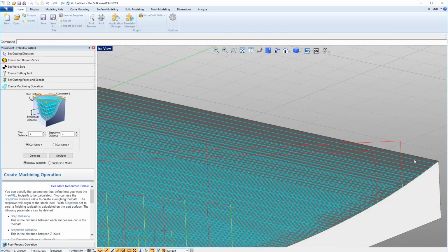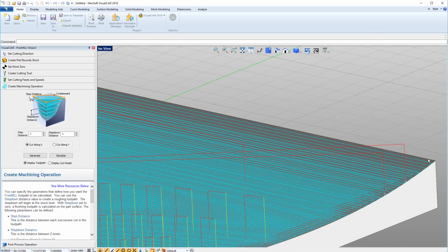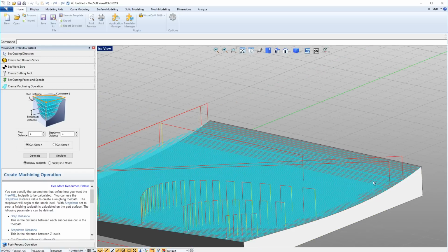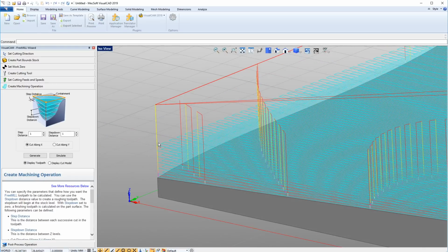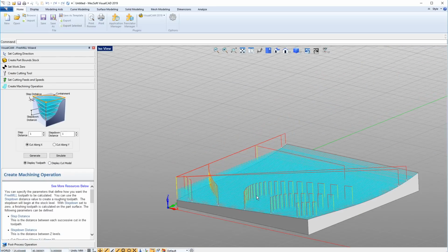So look up here, we can see my depth of cut is like 1 millimeter. So for that first bit up there, the whole depth of cut is right on the surface. So you can see those lines. That's the tip of the tool. It's following those lines on the surface. And then out here in space, you can see the lines are just sort of floating there. So that would be a flat bottom. But it keeps working down, flat bottom, flat bottom, flat bottom, flat bottom, till like after what, 1, 2, 3, 4, 5, 6, 7th pass, it will get to that final depth cut right on the surface, and you will have a nice undulating surface cut into your stock material.